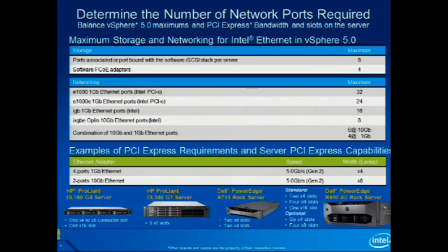The point that, I mean, obviously you have access to that information, and the piece that I want to make the point on is that a 2-port 10 gig Ethernet adapter requires a PCI Express Gen 2, or 5.0 gig speed, with 8 lanes, so by 8, in order to hit line rate on both ports bidirectional.